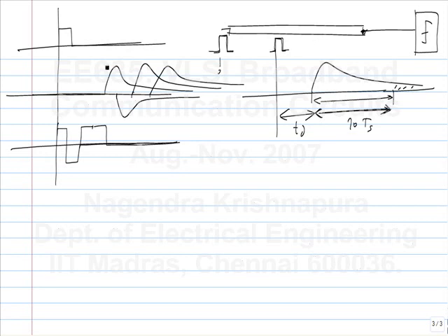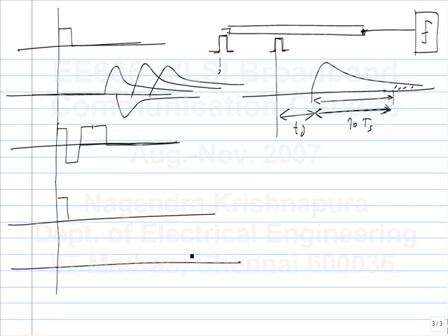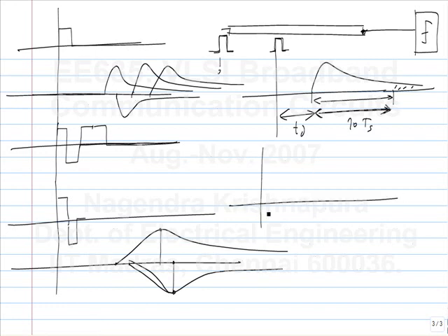And a lot of precursor ISI is because, let's say the response to a single pulse looks like this, where this is the bit interval, and the response to the next pulse would look something of this sort. So the peak of this pulse is here, the peak of the next pulse is here, and the second pulse has significant contribution even at the peak of the first pulse. So you can have effect on symbols before and after. That's because you can have a lot of delay. At least there are filters which have pulse responses like this.